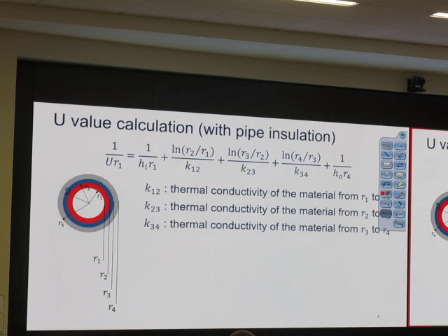Alright. The next trick that sometimes people fail is calculating the outer pipe diameter. I have a pipe diameter of 5 inch, and I have an insulation layer thickness of 1 inch, that is delta. So 5 inch is the outer diameter of the pipe.